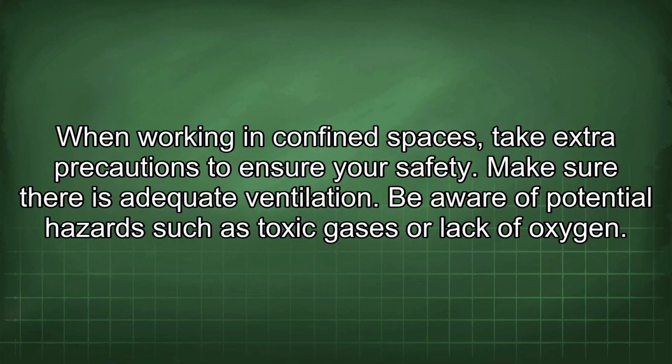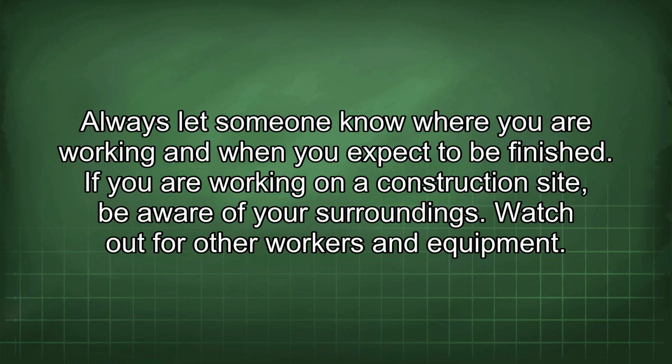When working in confined spaces, take extra precautions to ensure your safety. Make sure there is adequate ventilation. Be aware of potential hazards such as toxic gases or a lack of oxygen. Always let someone know where you are working and when you expect to be finished.